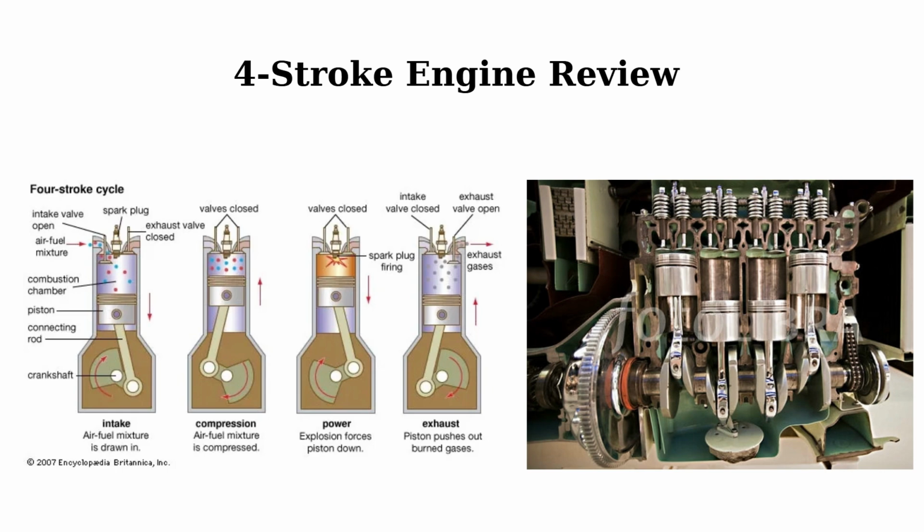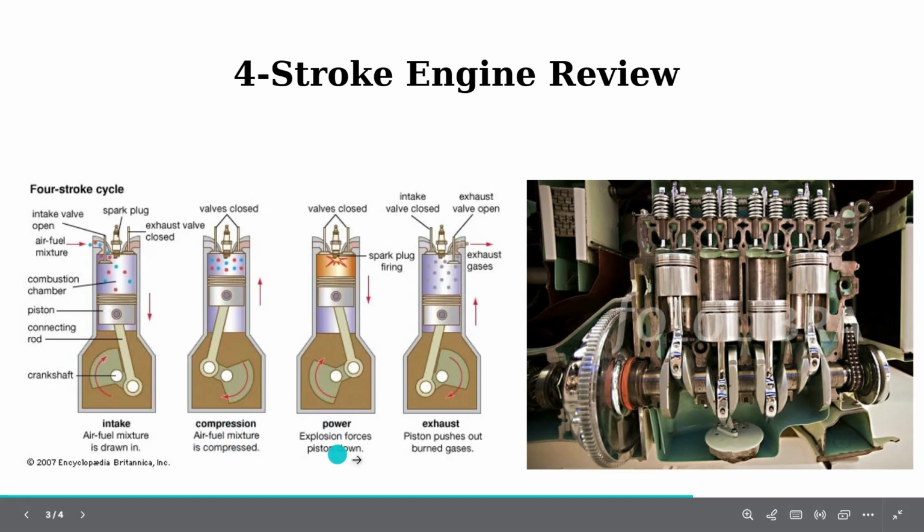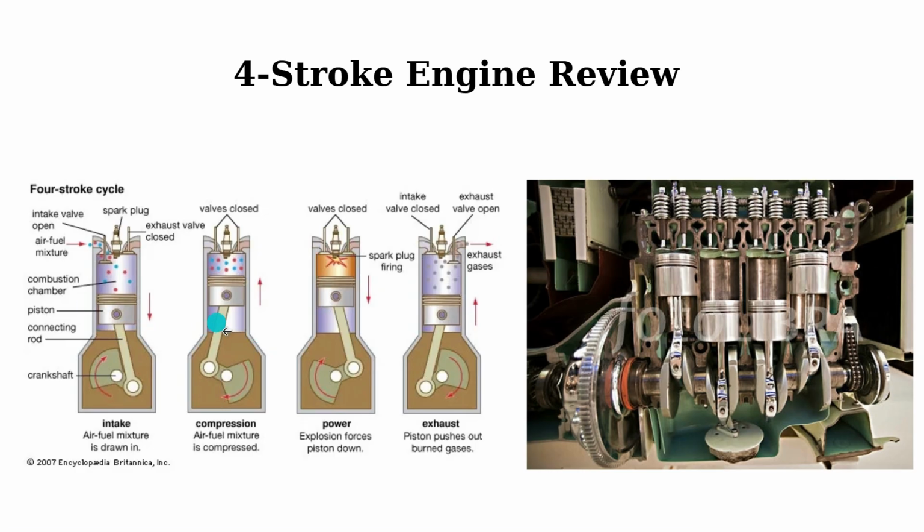These four strokes are intake, compression, power, and exhaust. Each stroke has a specific function, and all of them must happen in the correct order for the engine to work properly. This is so important, correct order. During the intake stroke, the piston moves downward and the intake valve opens. This allows the air-fuel mixture to enter the cylinder.